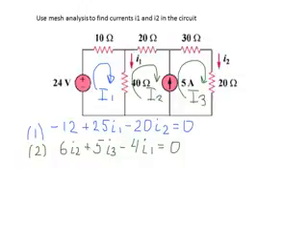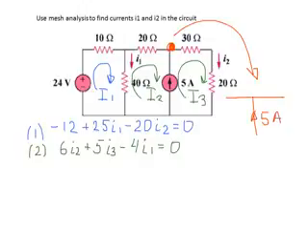How to do this? Let's look at the upper node, where the 5 amps is coming in. So I just draw this node larger. The current of 5 amps is coming into the node. And what other two currents belong to this node? This is the current I2, which is also coming into the node, so we put the arrow in, and that will be current I2.